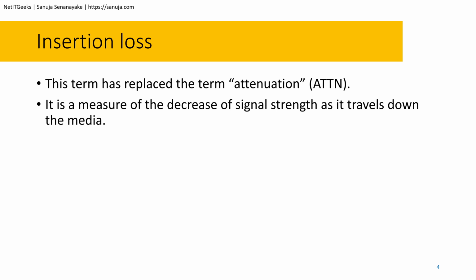Cable quality is another one. Poorly manufactured cables may have a higher resistance. Guess what higher resistance causes? Well, signal attenuation. Also poor insulation or inconsistent twist within that poor cable quality could cause a greater insertion loss. Another one that some instructors may forget is the temperature.